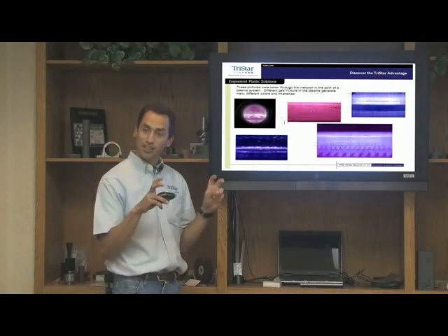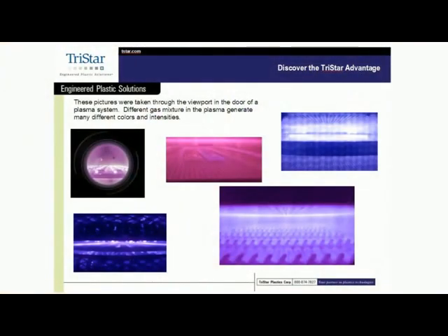When the magic time happens, step 3 happens, you can definitely tell something's happening inside the chamber because you do get a glow discharge. And each of these glow discharges has a characteristic color based on the gases you use. In some cases, we have the pale pink and blue, and we also have this one right here, which is a UV emission from oxygen.